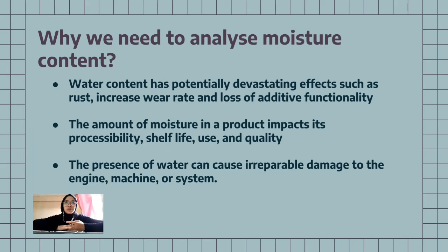So why do we need to analyze moisture content? Water content has potentially devastating effects such as rust, increased wear rate, and loss of additive functionality. Next, the amount of moisture in the product impacts its processability, shelf life, use, and also quality. And lastly, the presence of water can cause irreparable damage to the engine, machine, and system.